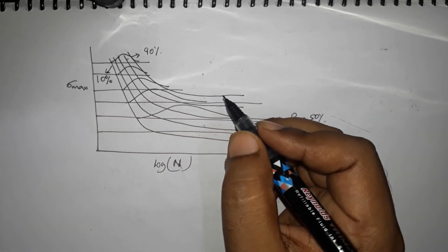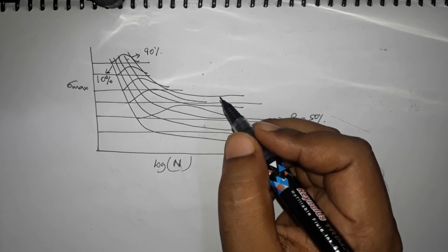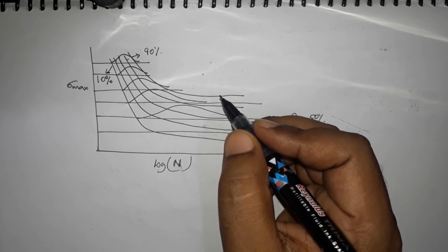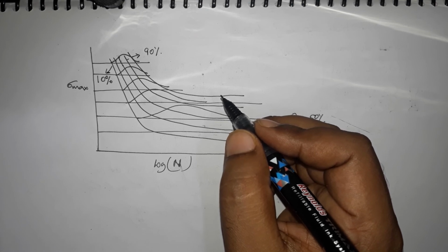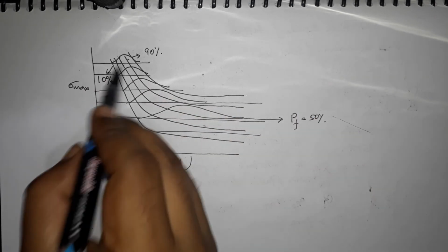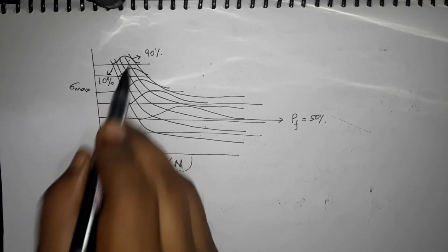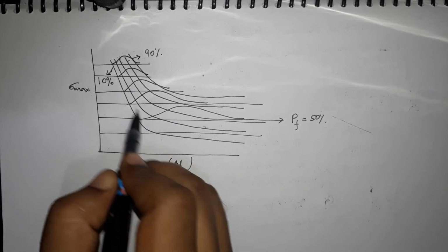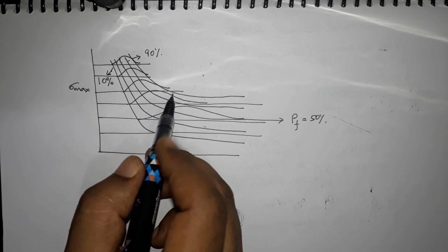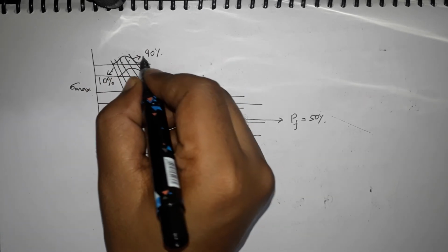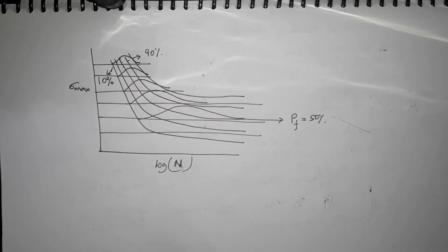is not good, because you are hitting the extreme and you usually don't have a sufficient amount of data to define the lower bound. So what you can do is this kind of test, and then if your component is beyond this 90% probability of failure, then you can say that you are safe. Okay, so this is how we deal with the statistical problem of fatigue failure.